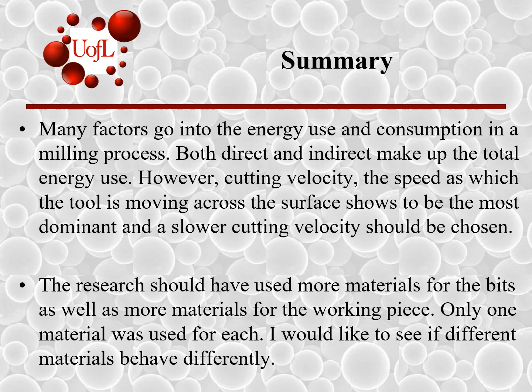Both direct and indirect make up the total energy use. However, cutting velocity, the speed at which the tool is moving across the surface, shows to be the most dominant, and a slower cutting velocity should be chosen because it showed that it had the most effect, and a slower cutting velocity led to less energy consumption.